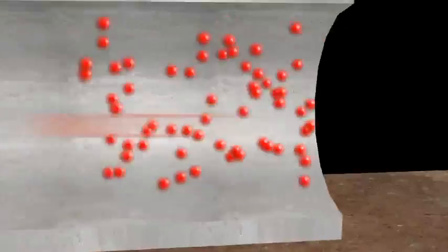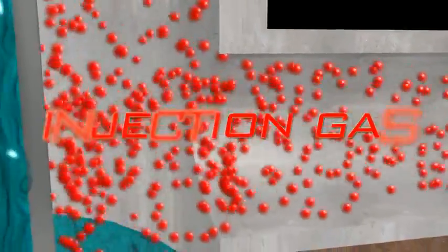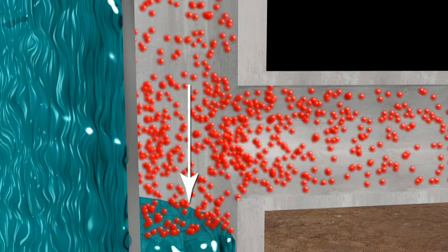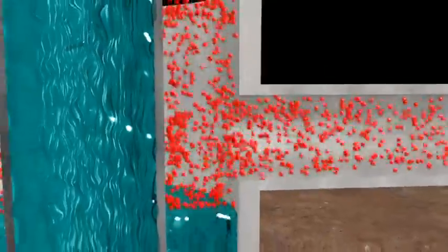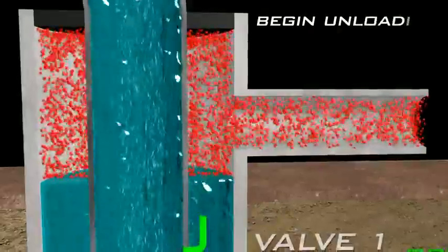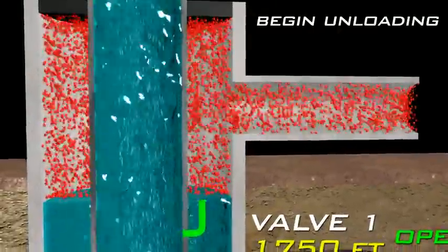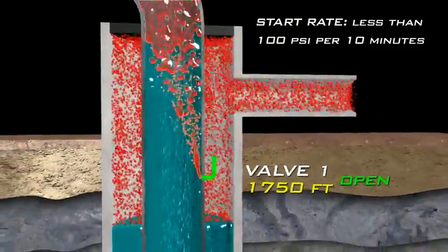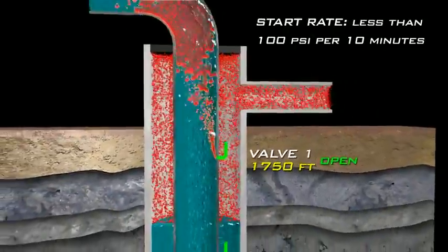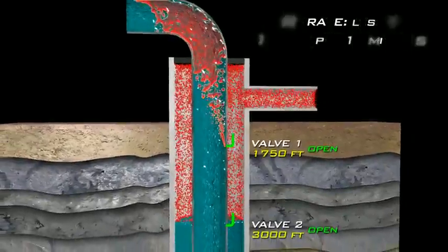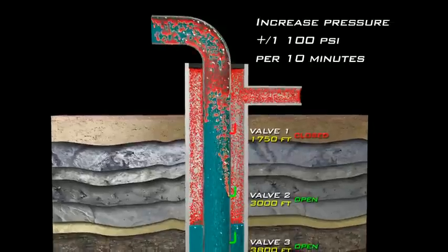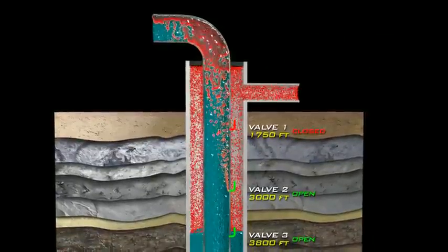When gas injection begins, the fluid levels in both the tubing and annulus are at the surface. The pressure of this fluid holds the valves open. As the gas is injected down the annulus, fluid from the tubing and annulus are being U-tubed through all valves. The annular fluid unloads past the first valve, and the gas injection aerates the liquid above the valve, decreasing its density. As the fluid continues to unload below the next valve, the gas injection transfers to that valve. The annular pressure decreases, and the top valve closes.